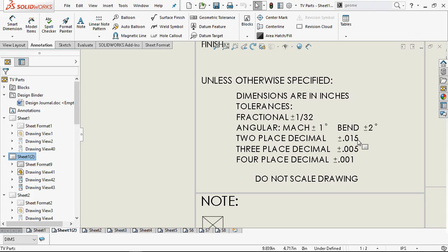All right. Now, cut it and hammer to fit. Type tolerances. The commonly accepted machine shop, plus or minus 5 thousandths is a general tolerance. All right, that is still a pretty big hole to fall into. I mentioned that under 4-place decimals is what it is you're really trying to control.